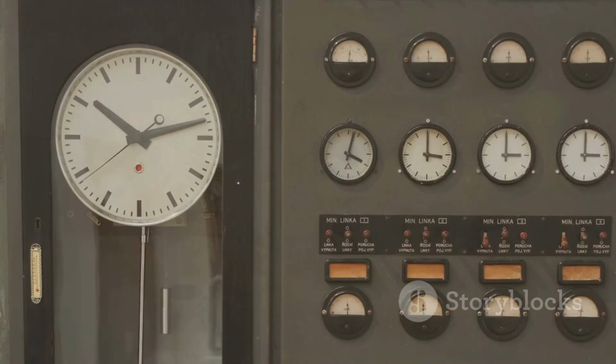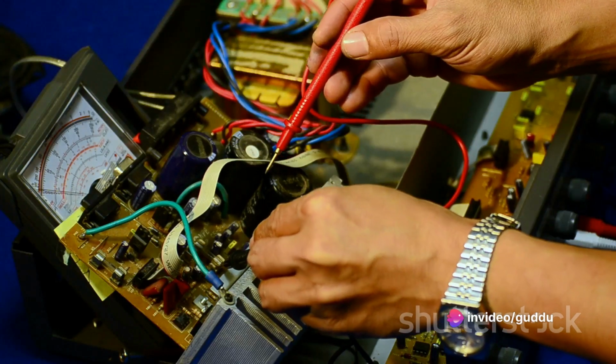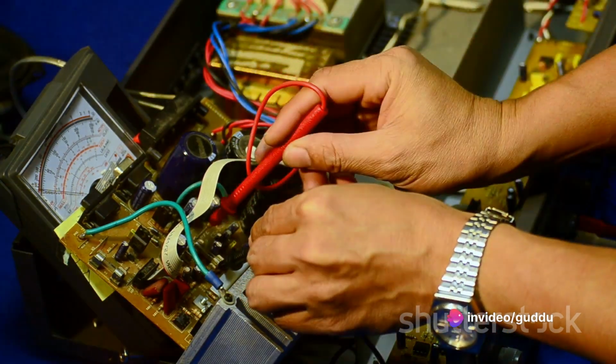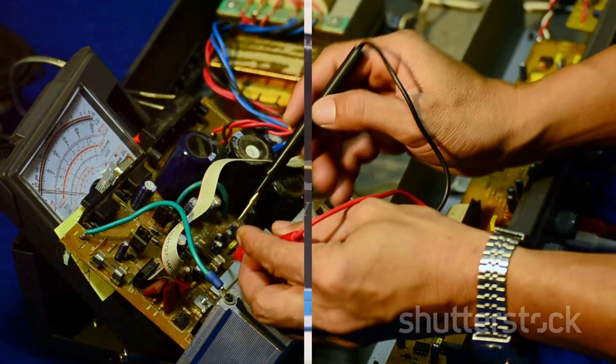Our next activity is to convert the given galvanometer into an ammeter and voltmeter of desired range and verify the same. Connect the necessary shunt resistance for the ammeter and series resistance for the voltmeter. The readings should match the expected values.